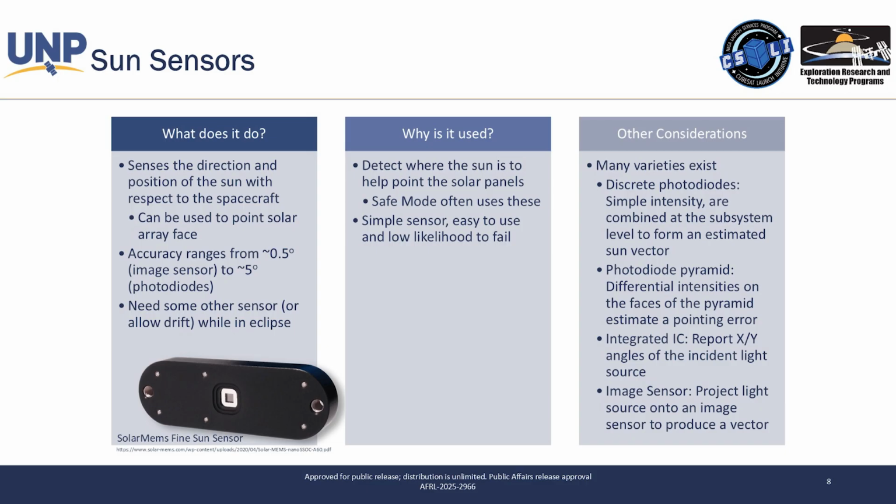They can work better when you're out at like geosynchronous orbit or other deeper space places. So we use this mostly when your spacecraft's more in safe mode to just determine where's the sun, get my panels on that, generate power. They're very simple. Usually they're literally photodiodes, such tiny little solar panels, and you can measure the voltage curve across that. As this photodiode rotates off of the sun, you can measure that angle based upon the voltage curve. So you can build these at home as well.